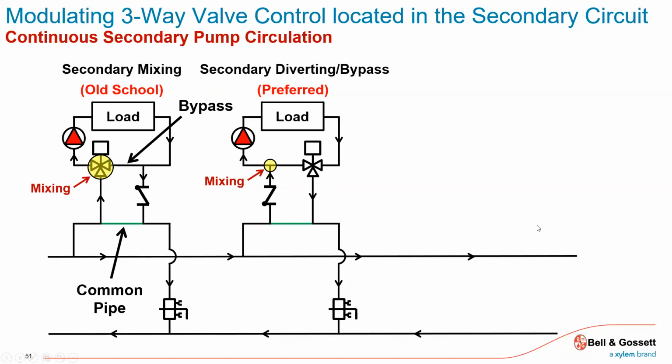One of the concerns is when that valve goes to close and says, hey, I don't need more heat, I'm okay right now, and I close off that port, as the temperature drop takes place, I'm missing my pressurization. I'm missing my expansion tank. And I can have some rapid drop in pressure in that closed loop.